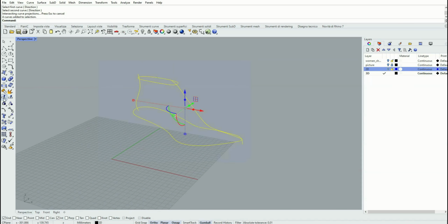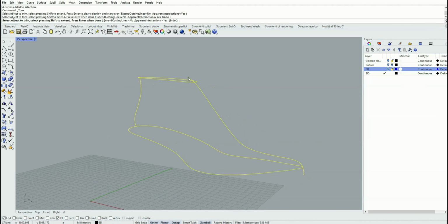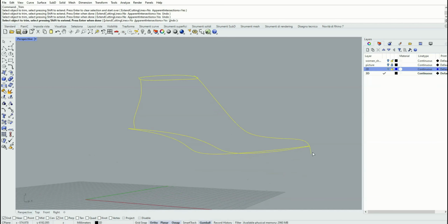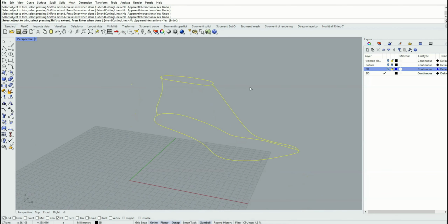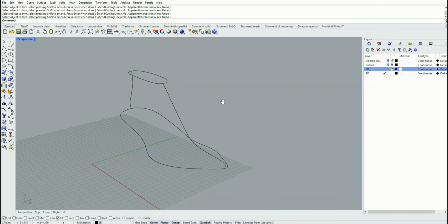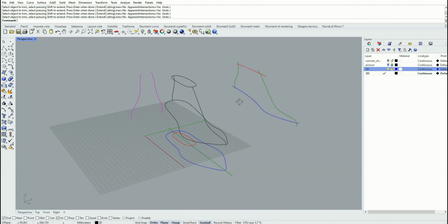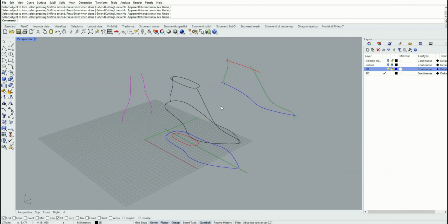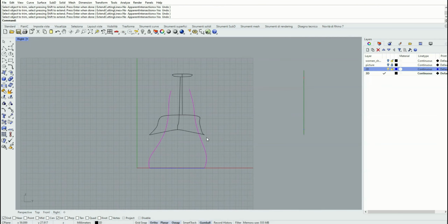We can go on by trimming out the exceeding parts of curves. Be careful because the trim command works in a specific view. In this case, we are working in perspective, so be aware of having cut off all exceeding curves. Okay, turn on 2D layer, go to front view, which in my case is right view, but it's just a matter of name. Front in reality, I mean.